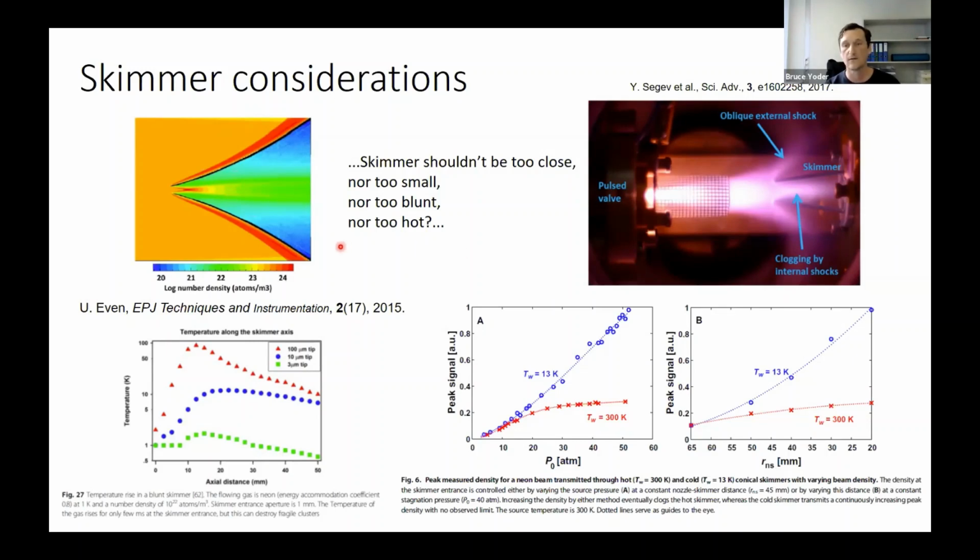So severe loss of the beam intensity is caused by the shockwave structure near the skimmer entrance, you see here. To achieve the best transmission results for intense molecular beams, like for example from an Evans-Lavie valve, it's often necessary to employ a large diameter skimmer, say 2 to 4 millimeters, and move the skimmer 10 to 20 centimeters downstream from the nozzle. These requirements need to be taken into account when you set up your experiments and design source chambers.